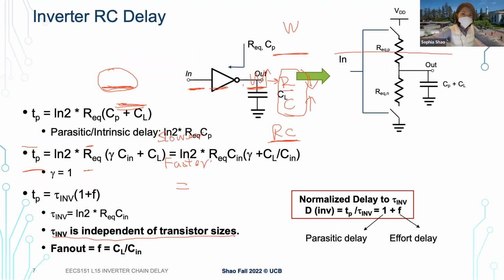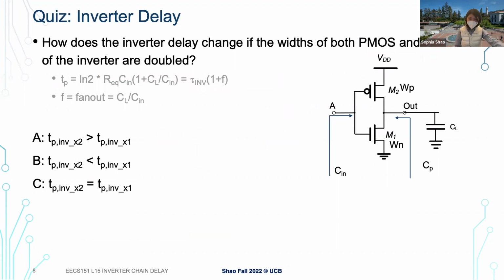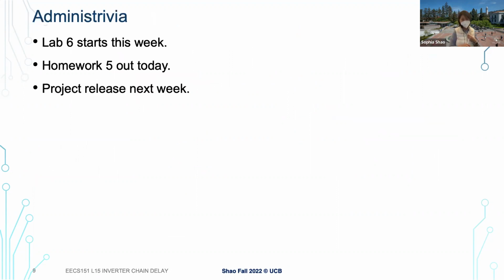Thank you. Yeah, that answers it well. Thanks. Right. So the resistance does change. It just cancels out because the capacitance also changes. Okay, good question. So now we see when people say make a bigger transistor, what they are trying to do here is basically modulate the delay change.